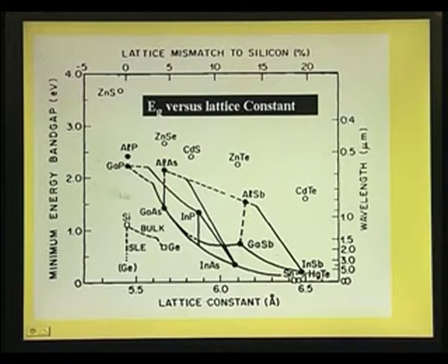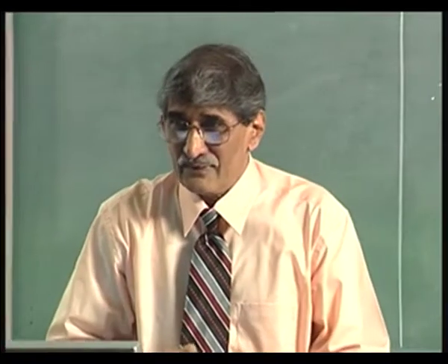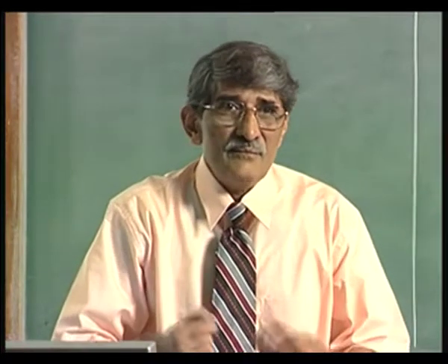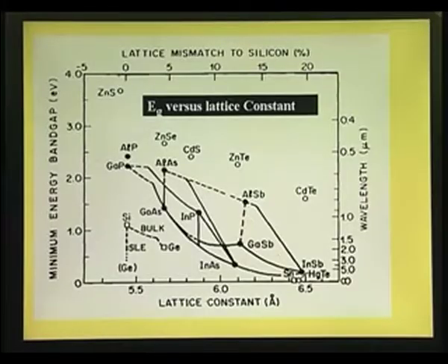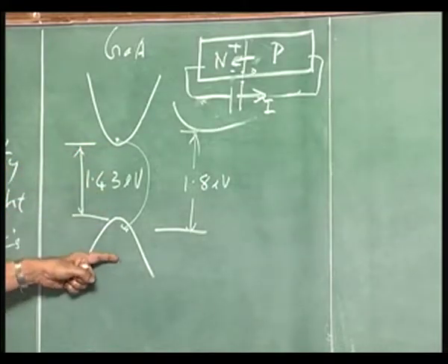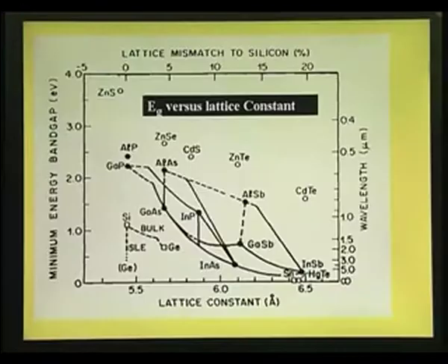Now, let us take this gallium phosphide and gallium arsenide. You can make a compound which consists of gallium, arsenic and phosphorus, gallium arsenide phosphide or gallium arsenic phosphide, whichever way you want to call it, a ternary. So, what is shown here is you can make a ternary using gallium phosphide and gallium arsenide. Now, remember, gallium arsenide is a direct band gap semiconductor. We have explained all that, whereas gallium phosphide is an indirect band gap semiconductor.